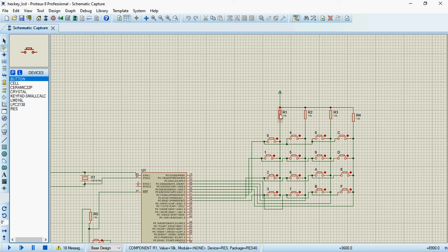And similarly use a power supply. So power supply you can find it from this end. So here you have the node, device pin, terminal nodes. In this you have to pick power. I have already picked, so I'll just keep cancel now. In your case you have to use it, and use also resistors. So resistor, in my case I'll go to the component layout, generic resistor you have to select.